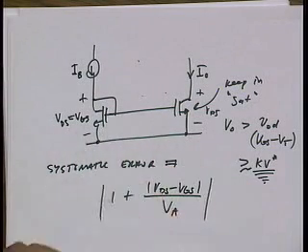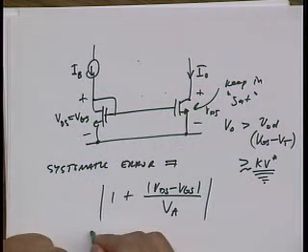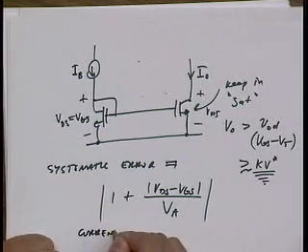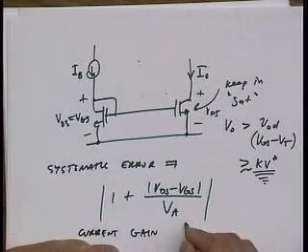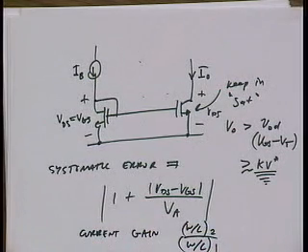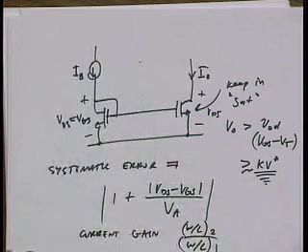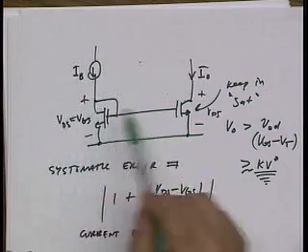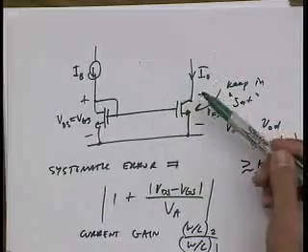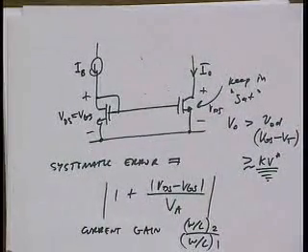Well, the nice thing about this current mirror is that you don't actually have to have the same W over L, right? I can have a current gain, which is W over L2 divided by W over L1. Okay? So this current gain could be 5 or 10. It's nice. That means that I can have one reference path running at low current, and I can gain that up for my actual amplifier, right? I don't want to waste current in my bias circuitry. Well, we'll re-examine that assumption.